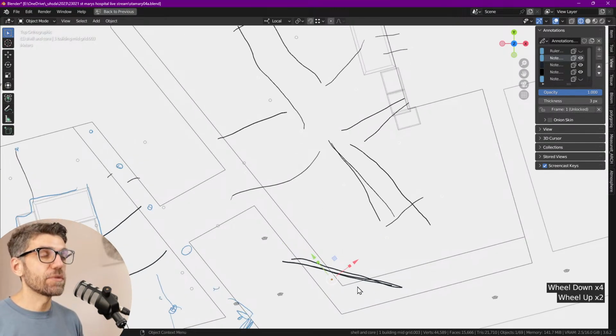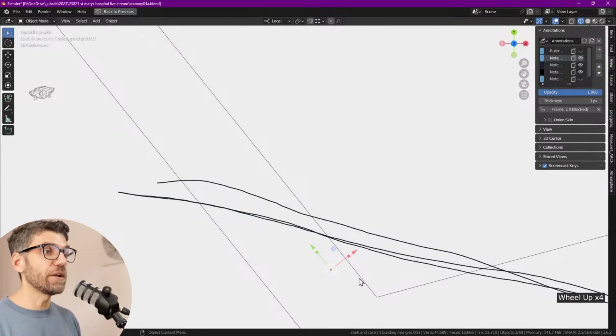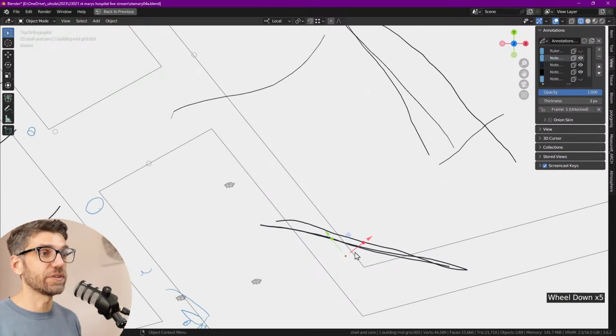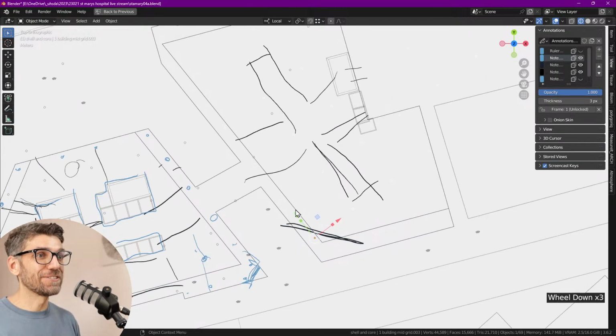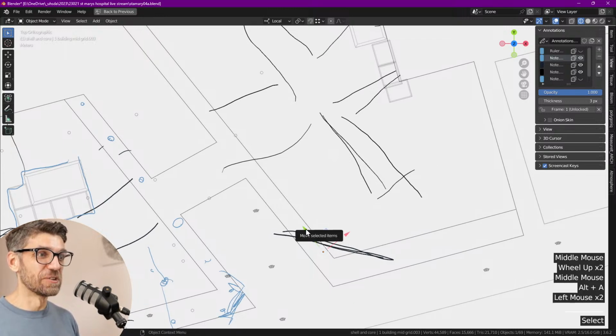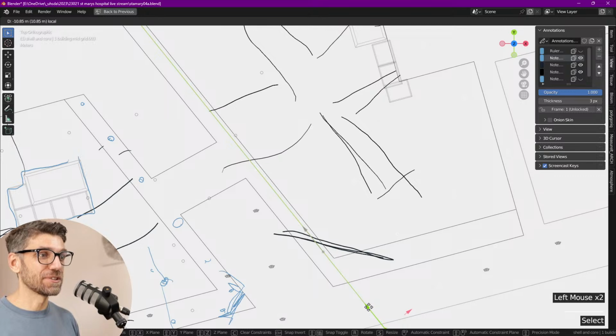Bottom setback, we don't care because that's the ground level, so it can be its own little thing and the columns reach back. But on the upper, we have to think about the columns. Right, so for example, this line was an upper line. Okay, what happens there? How do we connect it? We would need to have beams that go from this facade through the facade into there. And that looks a bit, how shall we say, neo-Gothic? That's a good way to describe it. Ugly, unresolved, other less nice words to use about that.